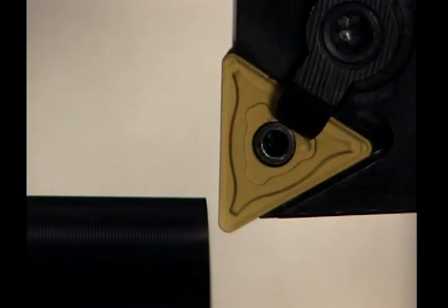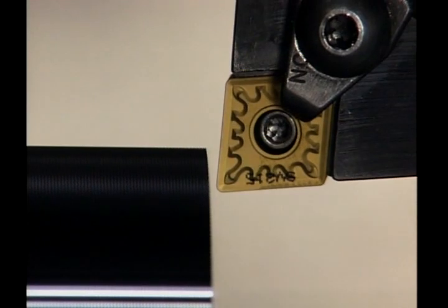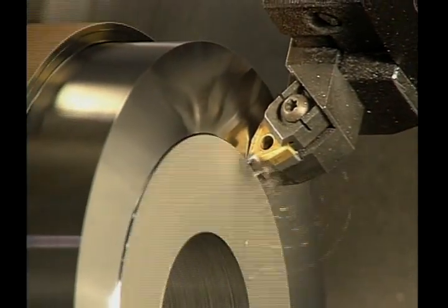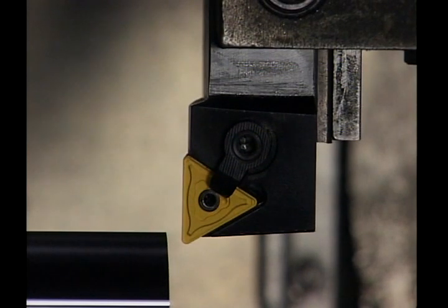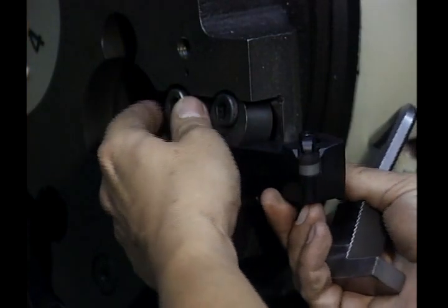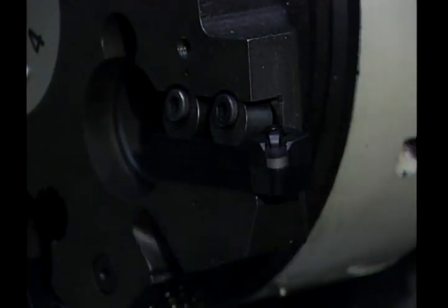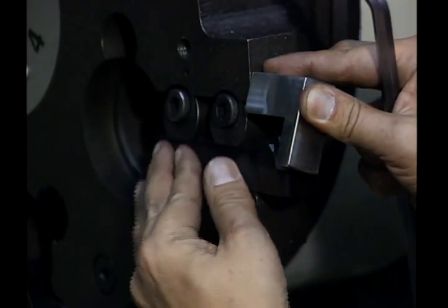When turning to a square shoulder, the tool holder should have a 0 degree lead angle or a -5 degree lead angle. In boring, a 0 degree lead angle is preferred, as it directs the feed force along the axis of the work, minimizing deflection. Some tool holders are designed for facing. The offset style tool holder lets work be performed closer to the chuck jaws and is generally chosen over the straight shank. Tool holders and boring bar should be positioned as far back in the turret or tool block as possible to maximize support. Overextended tools chatter and cause insert breakage.